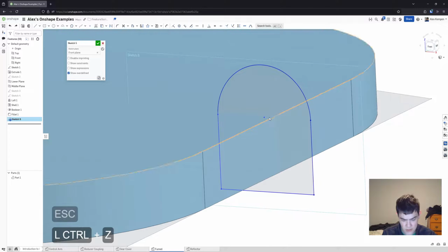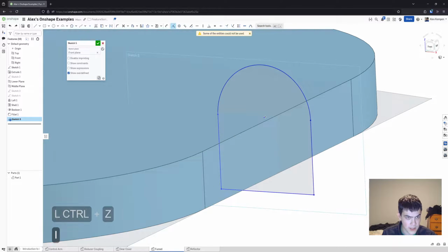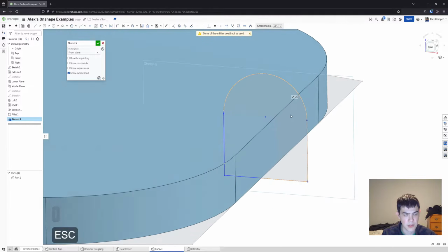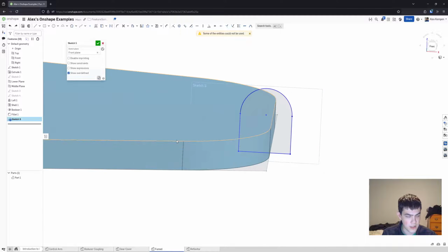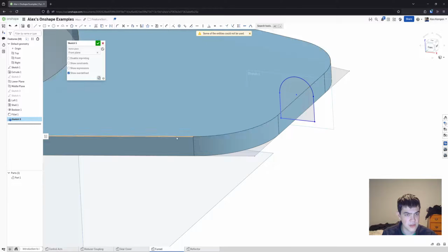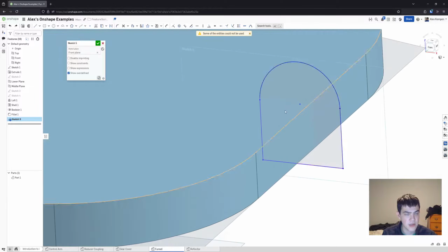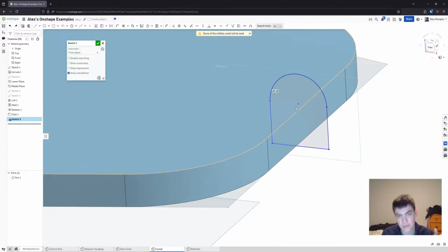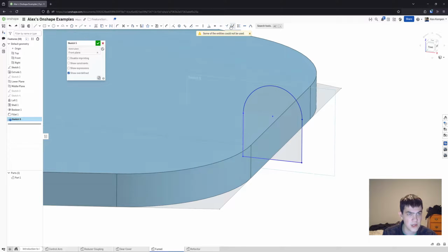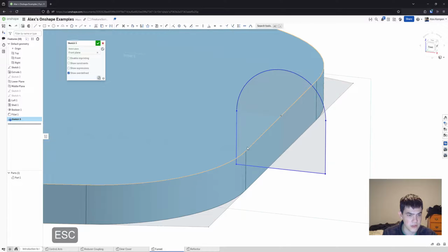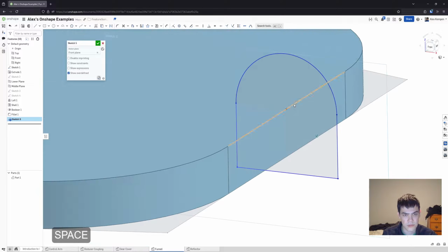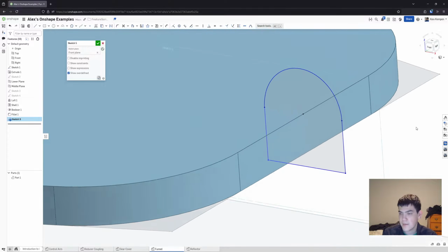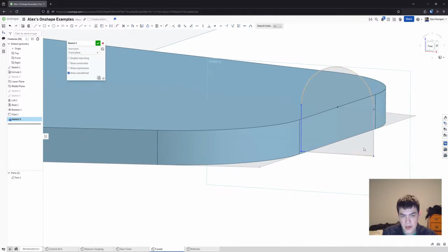And I think you could even coincident with the line here. No, because it's perpendicular. Normally coincident tries to project it onto the line, but because it's passing through or perpendicular to our sketch, you have to use the pierce constraint here, unless you're coinciding to a point, which it can just project. Obviously it's a little strange, perhaps. But yeah, so we can grab that.